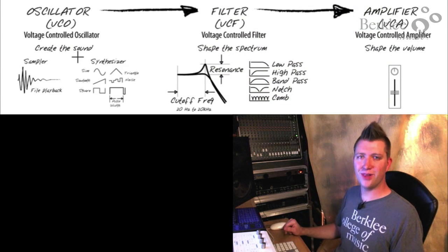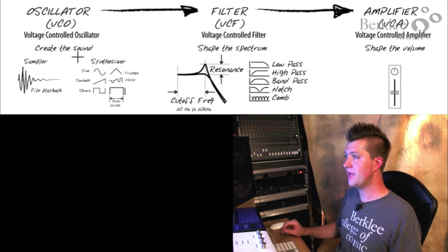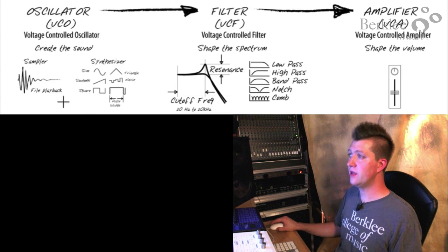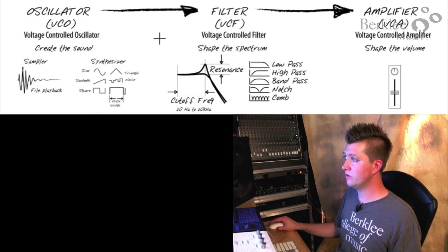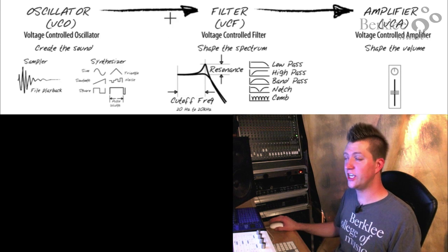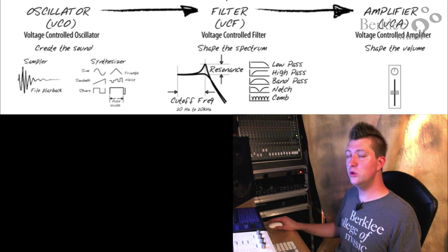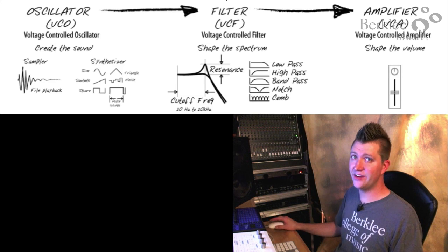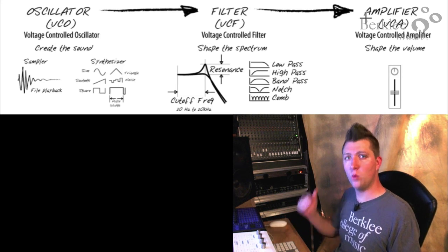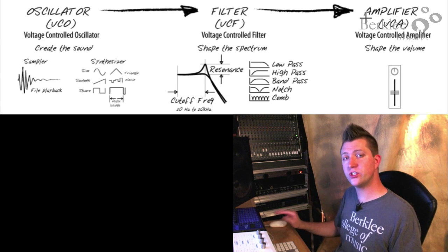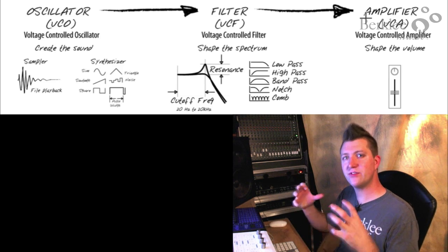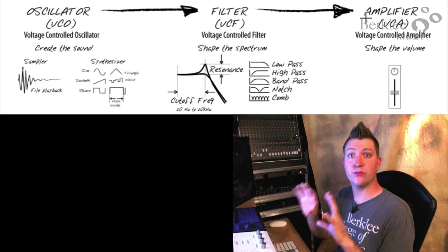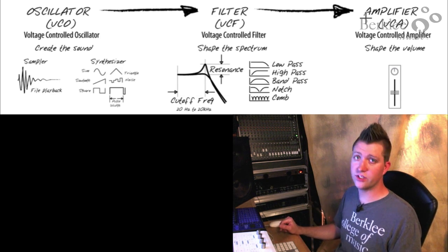We're looking here at a block diagram of a typical synthesizer. And a synthesizer really has three main modules. The oscillator, which creates the sound, often a very buzzy, harsh sound. The filter, which removes the portion of that sound that we don't want to hear, often reducing the high end. And an amplifier, which controls the level of that sound over time so we can craft the sound before we hear it. Now, that's the sound path or the signal path through a synthesizer.